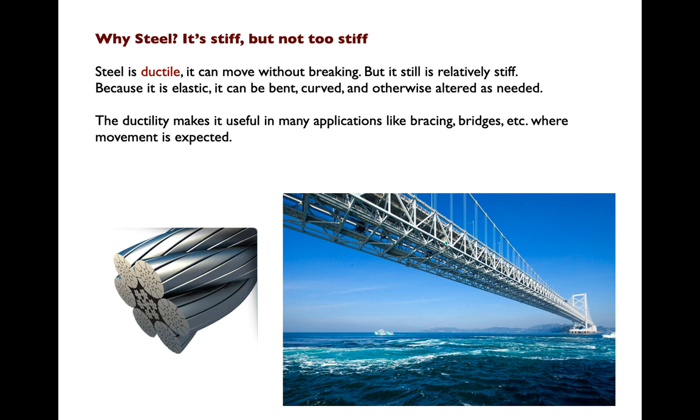This was not the case with cast iron, the predecessor to steel, which had to be molded into shapes and whose carbon content was so high that it was very brittle and couldn't be drilled or cut at all. We can do that very precisely with steel elements, and therefore we can fabricate them in ways that give us a lot of versatility on the job site, but also in very, very precision engineering, right? Precision production.